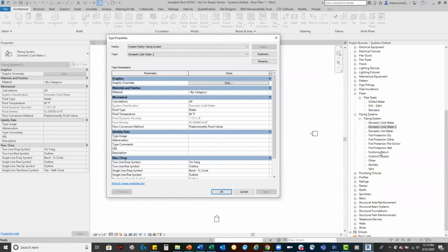If I'm doing anything else other than drainage, anything other than sanitary, and I don't care if it's gas piping, I don't care if it's medical gas piping, I don't care if it's vac piping, whatever the piping system is, it should go under this hydronic return or hydronic supply system classification based upon the direction of the flow. Okay, so like I said earlier, in the MEPPP, we leverage the 5: hydronic return, hydronic supply, domestic cold, domestic hot, and sanitary.